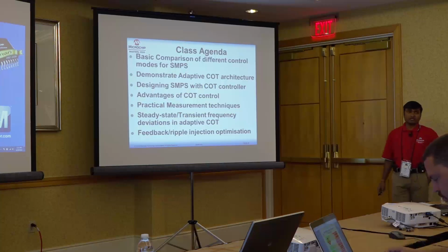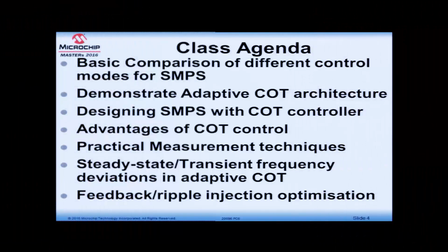This is our class agenda. Initially, we will go over a basic comparison of different control mode architectures available for switched mode power supplies, and we will demonstrate the adaptive COT architecture and the advantages it brings. We will understand the design procedure with the constant on time controller, and discuss its advantages compared to other traditional control modes.